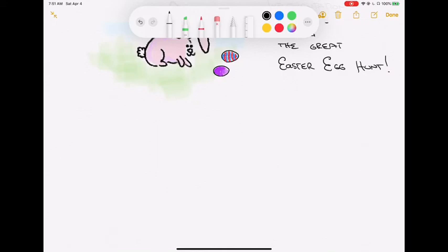To start this out, I think we'll just focus on a second order system. I focus on a second order system because it's the lowest order system that still allows us to have a general pole or zero, one that could be potentially complex. For a real system, if we have a complex pole, we know it has a conjugate out there. So you would take a pole and its conjugate, combine those together, and you'd get a second order system. Anything bigger than that, these structures are easily extendable. But the second order system is the fundamental building block, especially for real systems.